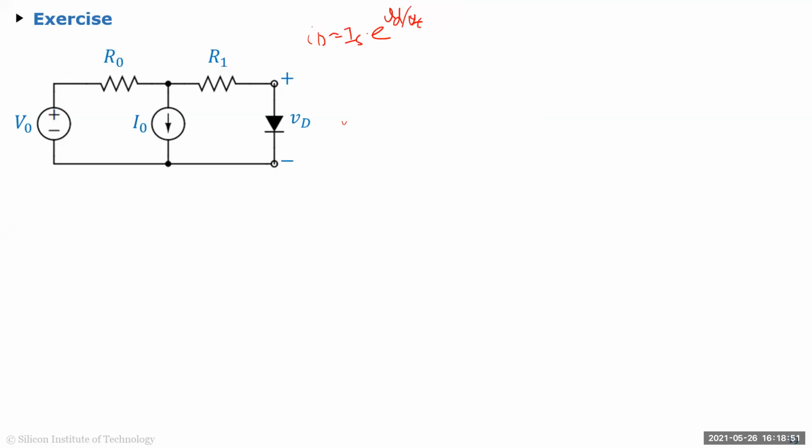Because the diode's voltage doesn't change a whole lot with the current. So the first thing you can do is just substitute it with a voltage source of 0.5 volts and solve it, right? So instead of trying to find out VD and ID for that, you can just solve it. The other method I wanted to show you is